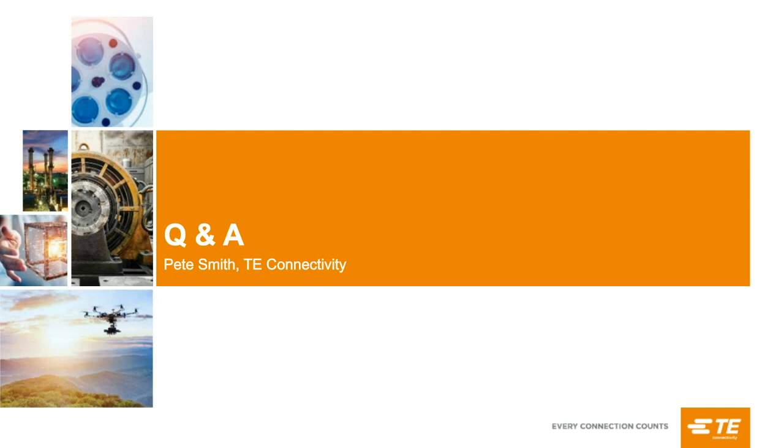So we take that analog signal from the sensing element and we put it into an A to D converter, as you suggest. We use a delta sigma type scheme for analog to digital conversion. It's a common scheme. It's used a lot. It's simple. It can be done in very low power and can be done at very high speed. So the answer to your question is yes, and we do it all the time.